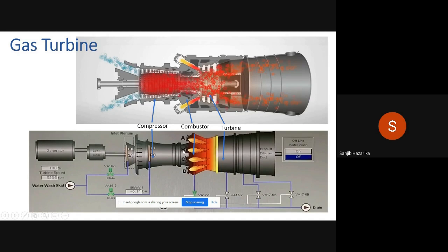The bottom part is showing how that gas turbine runs the generator. This gas turbine speed is around 5,236 RPM. There are gas turbines with variable speed as well. And for some gas turbines, the RPM needs to be reduced to maintain 50 or 60 hertz, which is required for a grid system.